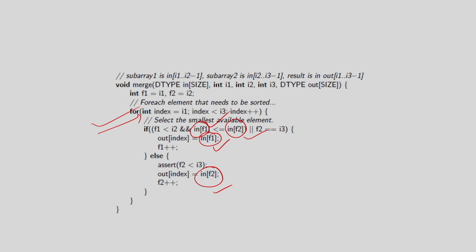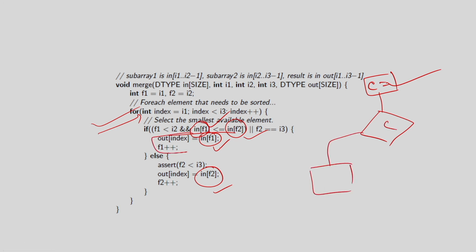Now the question is, does the high level synthesis compiler understand this? Can it understand that these are not 4 reads, these are 2 reads? Unfortunately, most compilers won't, because these operations happen in different basic blocks, right. Let me try to explain. So this is the condition, right. Some reading is happening, so this read will happen here. These reads, in 1 and in 2, will happen here, and then this condition will be calculated here, and based on the condition you will go here. This is the if block, and else you are going to do this, right.